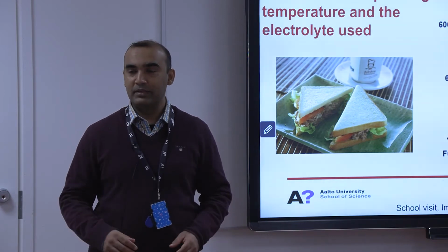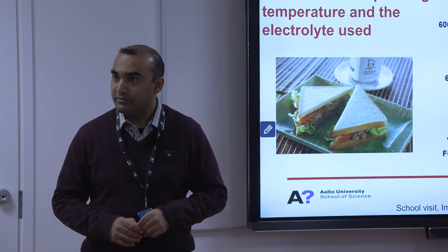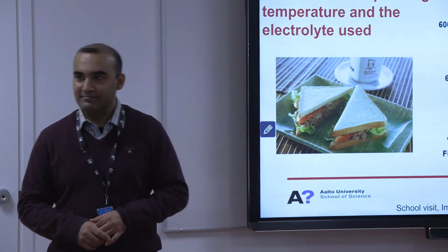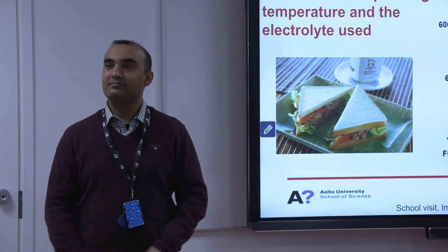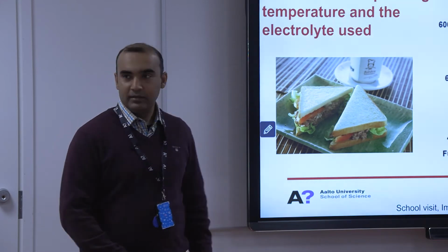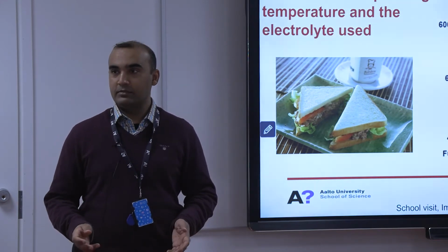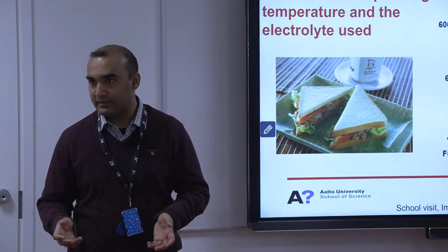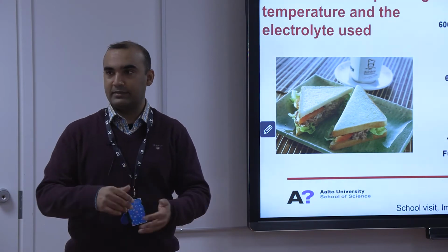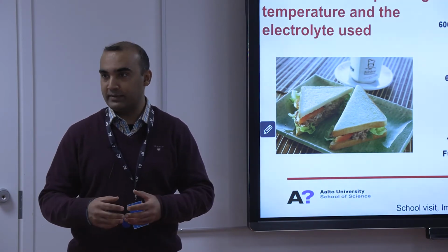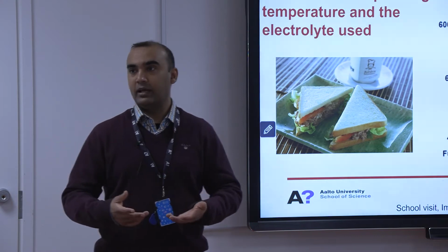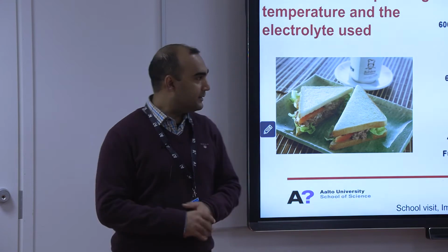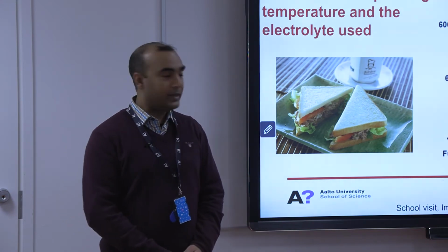Is there any mechanical device for heating a fuel cell if you use it in winter? Yeah, so you mean for the high temperature fuel cells? If you start your engine in Finland in winter, which is about 20 degrees below zero, you need to heat that. Yeah, and I think that's kind of easy, because in those kinds of setups, usually it's combustion of the gases. So for example, when you have gases, there's some kind of a place where you just mix those gases and they burn and generate heat. And once you get the heat, you start working in fuel cell mode. So basically it's possible.